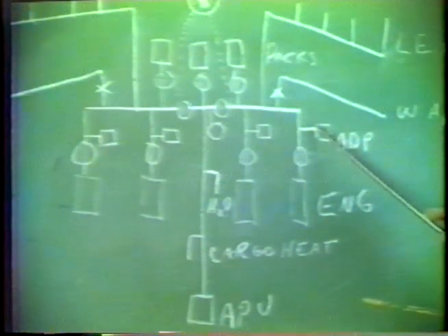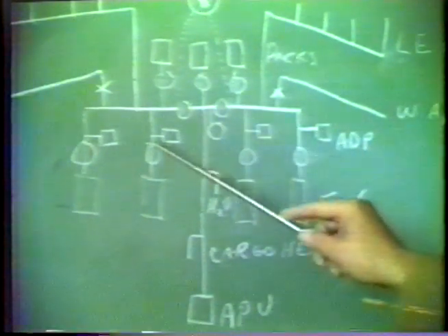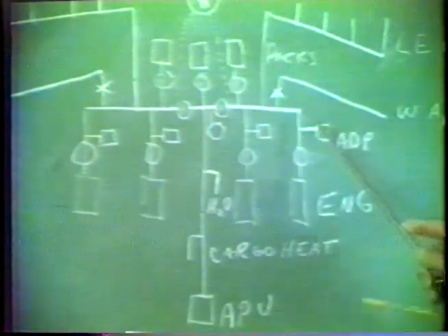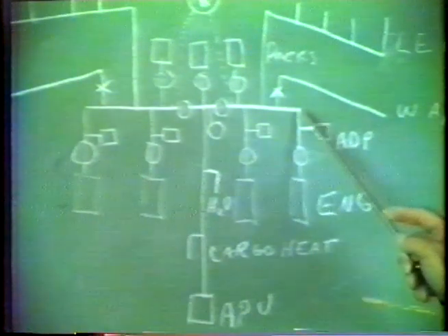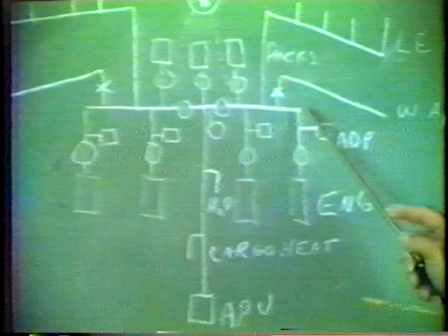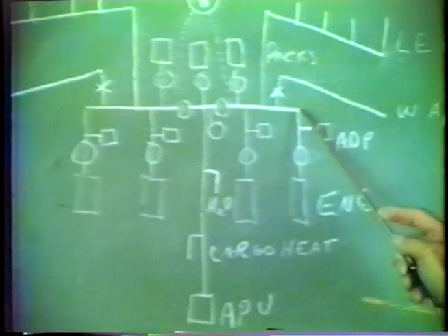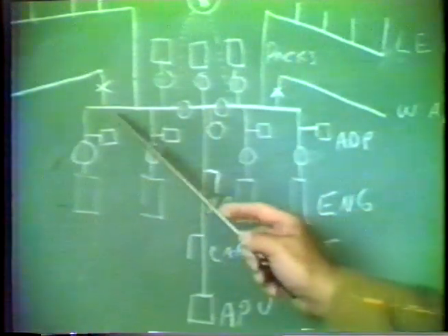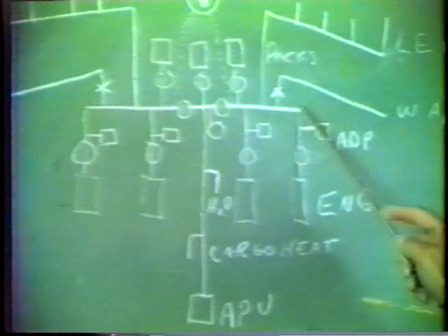Of course, there is a control valve for each of the air pumps, so you can operate them or turn them off. This comes into a large duct that goes practically from wingtip to wingtip and through the center portion of the unpressurized portion of the airplane, represented by what is called the pneumatic duct.